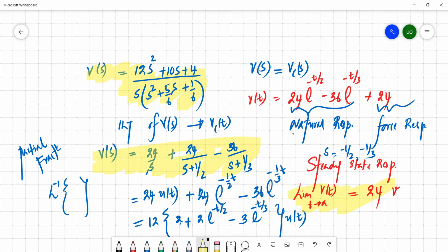Whatever the time domain quantities are, they are simply converted into the phasor domain by their corresponding models. We convert inductors to j omega L and capacitors to 1 over j omega C and so on. Then the entire time domain circuit is converted into the phasor domain and we do the calculation in complex form.